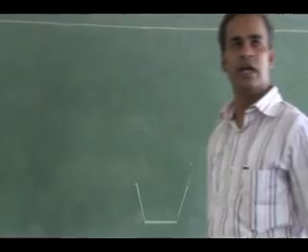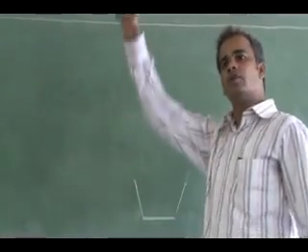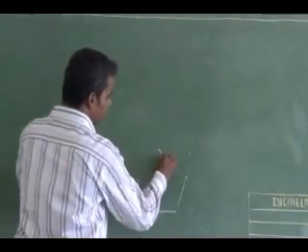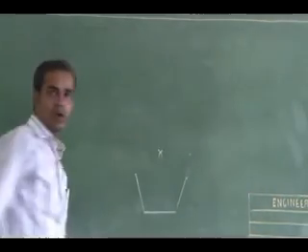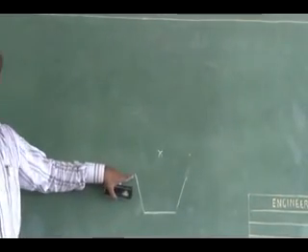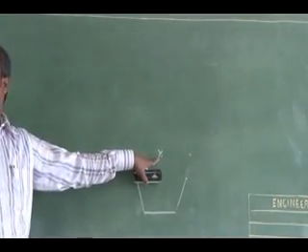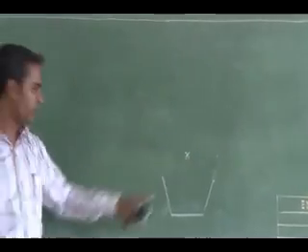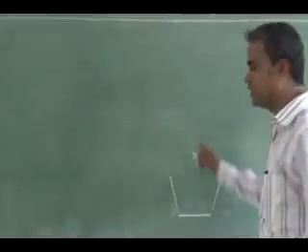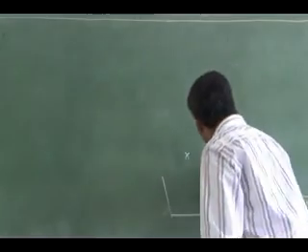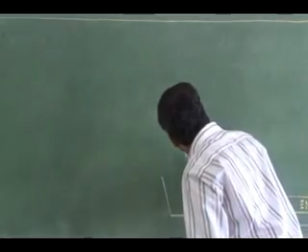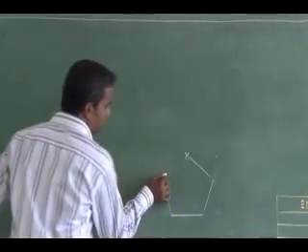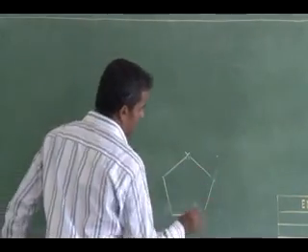Then to end up with the final corner, measure the same 20 with your compass to get the intersection. Using this corner I can have a 20 mm, and using the other corner I can have another 20 mm. The intersection will give me another corner. This is my pentagon.